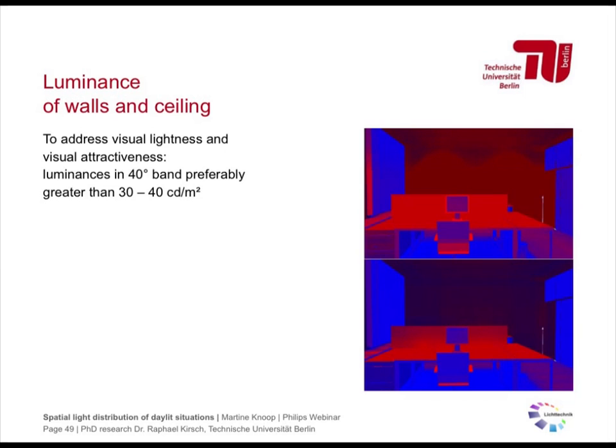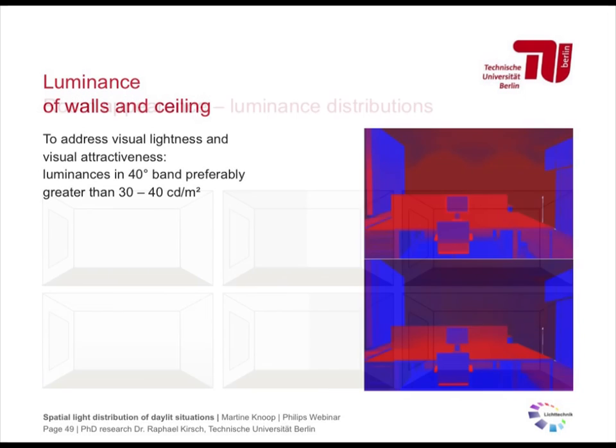In fact, he found that an increase from the typical European standard levels, approximately 11 candela per square meter, to 30 candela per square meter, balanced out the changes resulting from going from a horizontal illuminance in the surrounding area of 300 to 100 lux. So in fact, he said if we reduce the horizontal illuminance, we can use that lighting to increase visual lightness and visual appraisal in these situations.